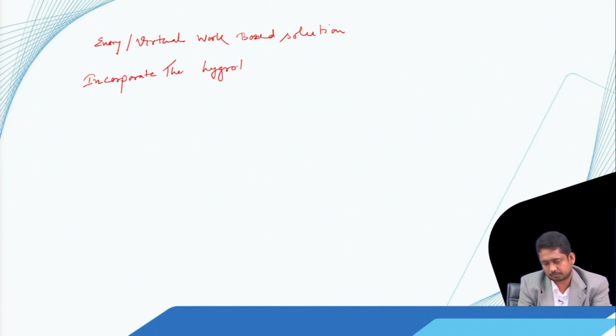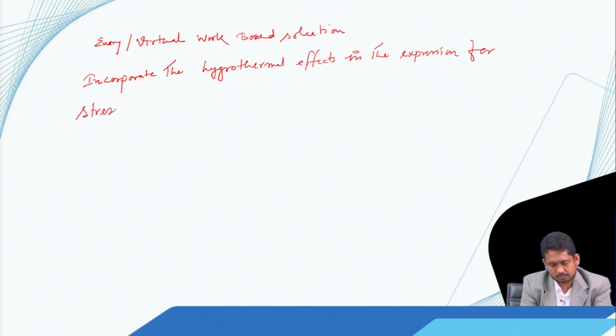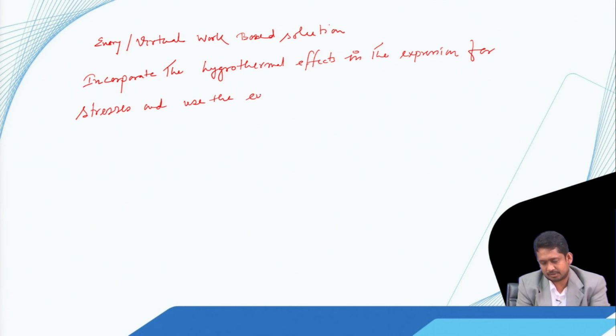For that we have to incorporate the hydrothermal effects in the expression for stresses and use the energy or virtual work equation. After that the procedure is the same, the only thing is that in the stress expressions the hydrothermal effect has to be incorporated.